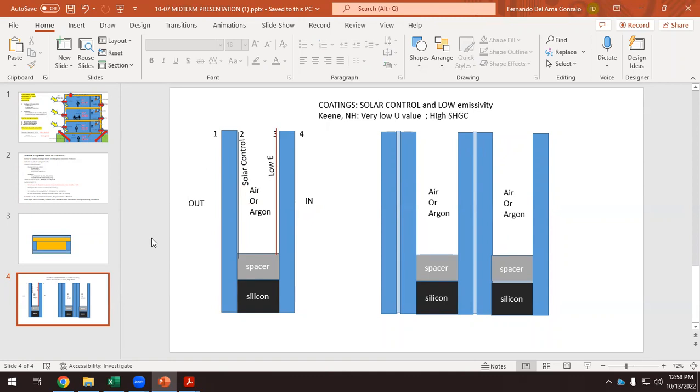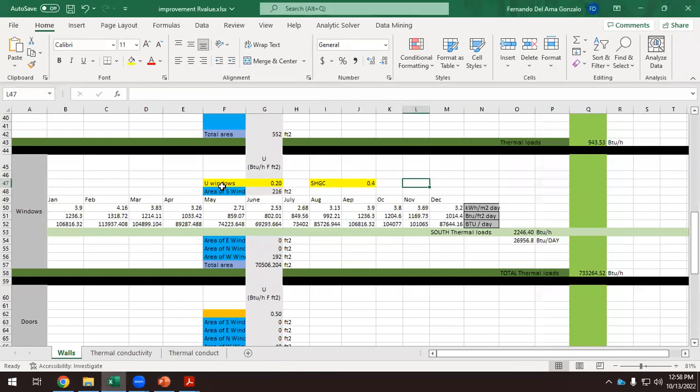So this is probably the most important decision in your project. What kind of glass are we using? Not in single family houses, because in single family houses we don't have a lot of glass, but in commercial buildings, that will affect the total heating loads. And it always happens in life: the better the product, the more expensive the product is. So you have a lot of coatings, laminated glass, it will be extremely expensive. But that's what we have to do. You have to find the catalog, minimum U value, maximum solar heat gain coefficient.